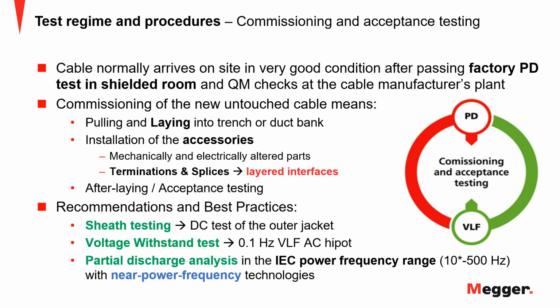You take it off the truck and then you start laying the cable. So this is the moment where damage can occur. First of all, again, sheath damage, so jacket damage. The jacket integrity can be compromised, which is important down the road because any sheath fault is an entry point for moisture, and moisture ingress will damage your cable sooner or later. And by capillary effect, this moisture will travel through the cable over time.